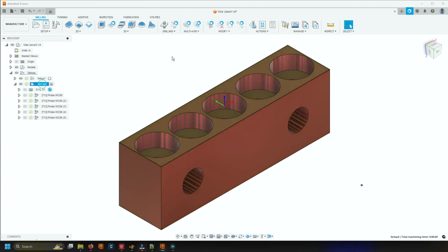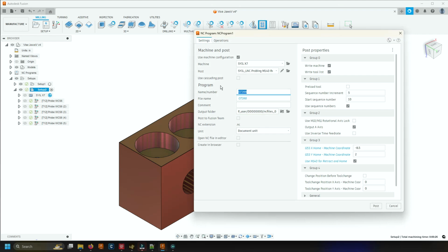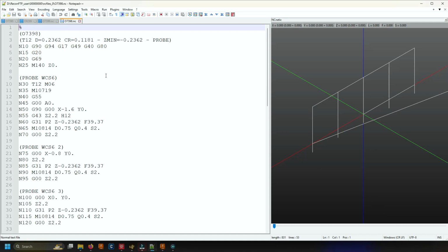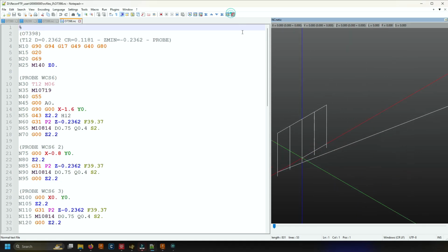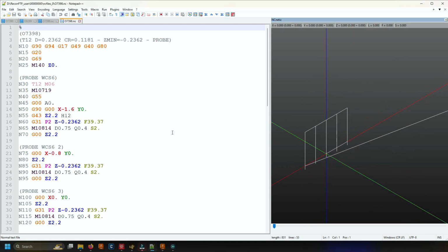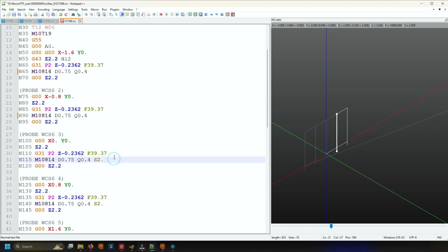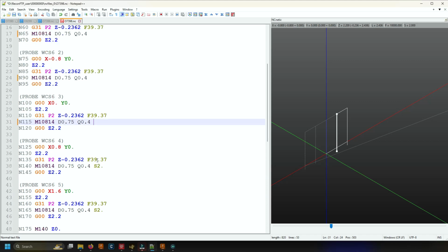We are going to post-process that file and bring it up in our editor. Pretty simple file. The notable thing that we want to make changes on is removing the S from all the probe functions. This is all we need to do to use this probe for inspection.